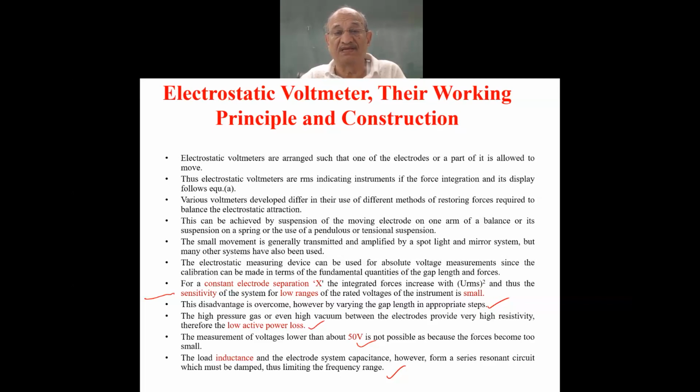But the problem arises at high frequency that the load inductance and the electrode system capacitance value, that is XL and XC, the inductive and capacitive reactances acquire different values. The inductive reactance increases, the capacitive reactance also increases. So that must be taken care of at high frequency.